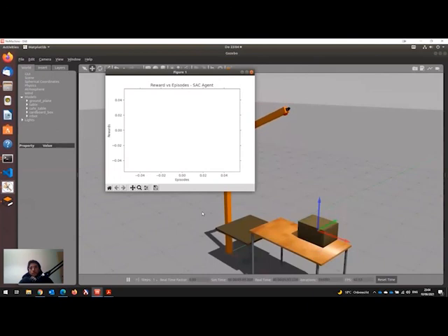I tuned the PID control to an extent to overcome this issue, even though there are still some spots where there exist position offsets to the desired pose. Due to this, a reward function based on the end effector frame and box frame cannot be used for the training process.